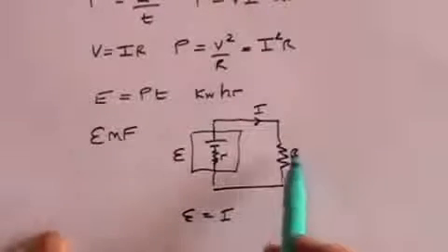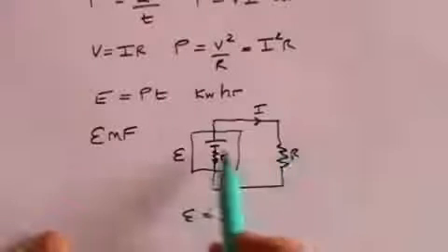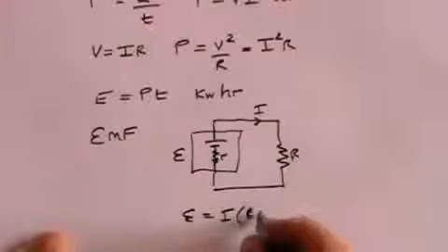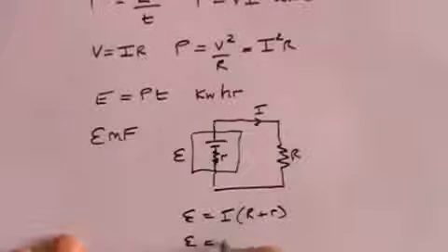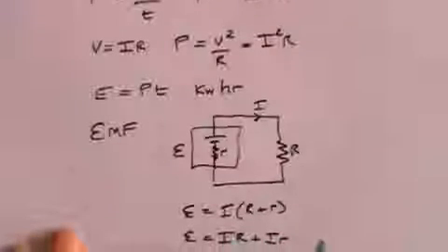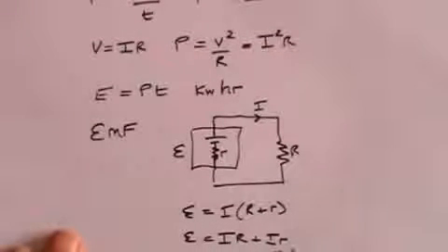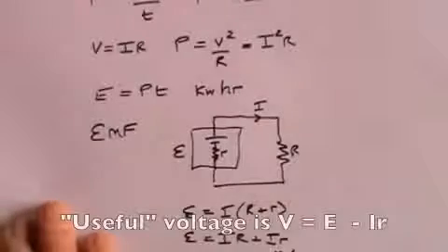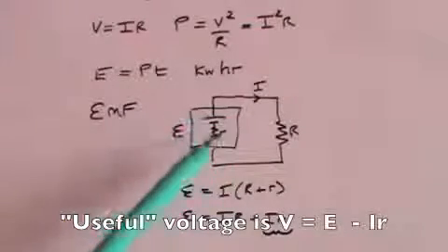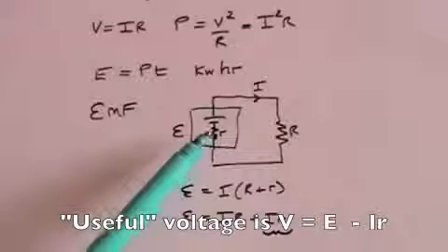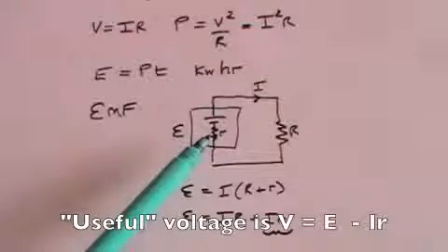But what is R? R is the external resistance and the internal resistance. And so you have that E equals IR plus I little r, and that is, as it were, the lost energy, because that's what's dissipated inside the battery and is often a reason why the battery appears to get warm.